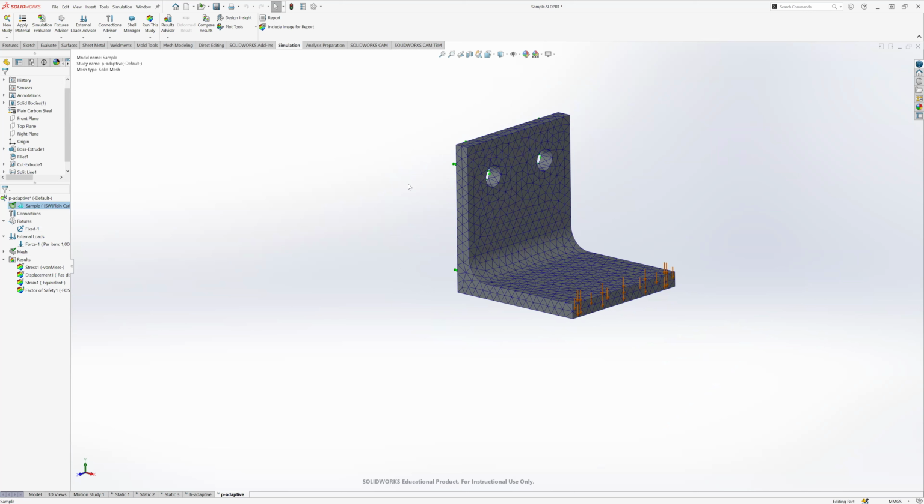Okay, so that's a lot about meshing. What I'll probably try to get into now is what if you're working with either an assembly or a part with multiple bodies in it. So I'll try to start getting into a little bit of that now. I'll just go and save this model. But I would say that's a pretty good overview of all the different things you have with meshing. Obviously, you can just manually do it. You can use mesh controls. You can use H adaptive. You can use P adaptive, to refine the mesh to your liking.